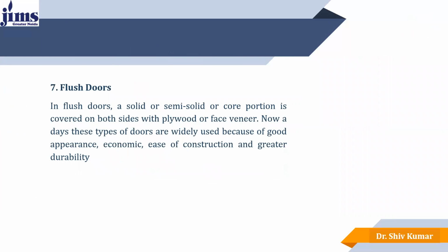The next is the flush door. In flush doors, a solid or semi-solid core portion is covered on both sides with plywood or face veneer. Nowadays, these types of doors are widely used because of good appearance, economic ease of construction, and greater durability.